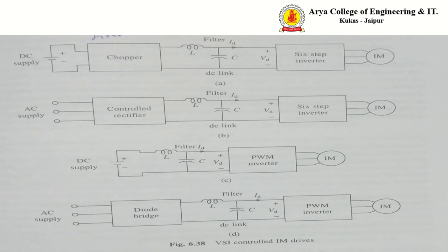Generally, MOSFET is used in low voltage and low power inverters. IGBT (insulated gate bipolar transistor) and power transistors are used up to medium power level, and GTO (gate turn-off thyristor) and IGCT (integrated gate commutated thyristor) are used for high power level.